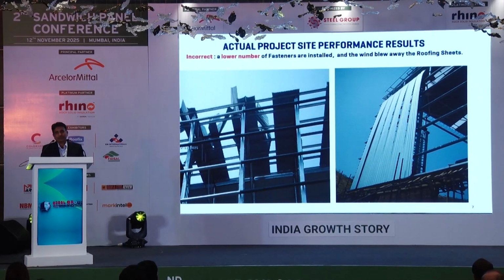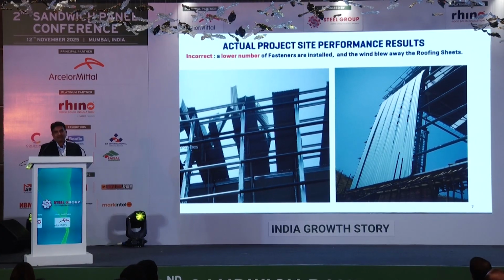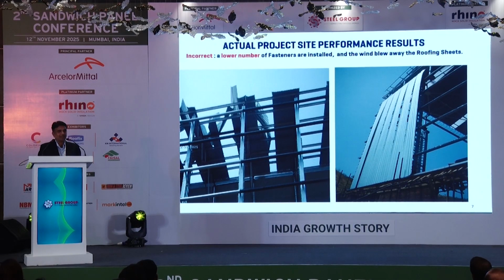This is a factory which was going to open the next day, and a day prior, because the number of fasteners installed was lower, the entire roof flew off. And you can see the number of screws installed while cladding as well. It's so low that the entire roof had to be replaced, which cost the owner quite a lot of money.